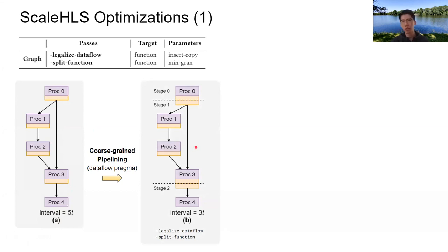And typically, the downstream high-level synthesis tools will have some requirement for coarse-grained pipelining. For example, typically, they will not allow a bypass path between different pipeline stages to avoid data pollution. So here, conservatively, we can split the original computation graph into 3 pipeline stages to avoid the bypass paths.